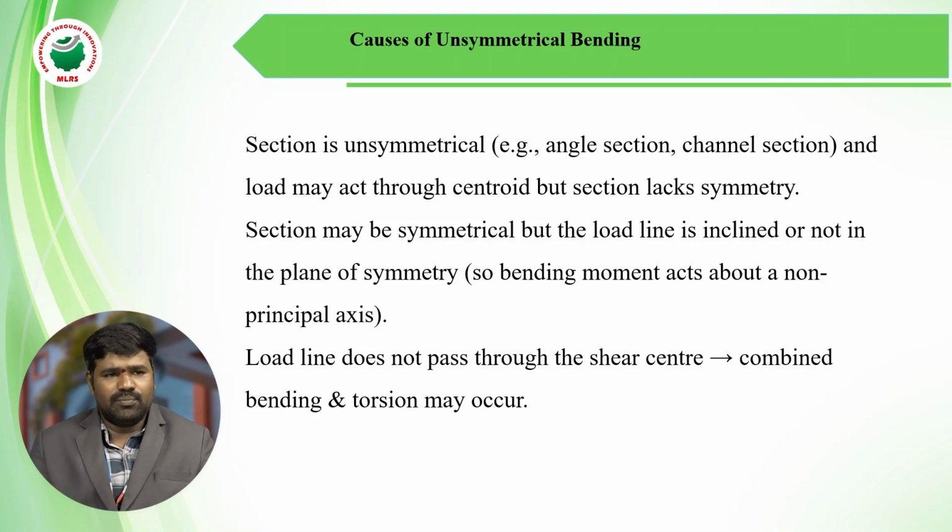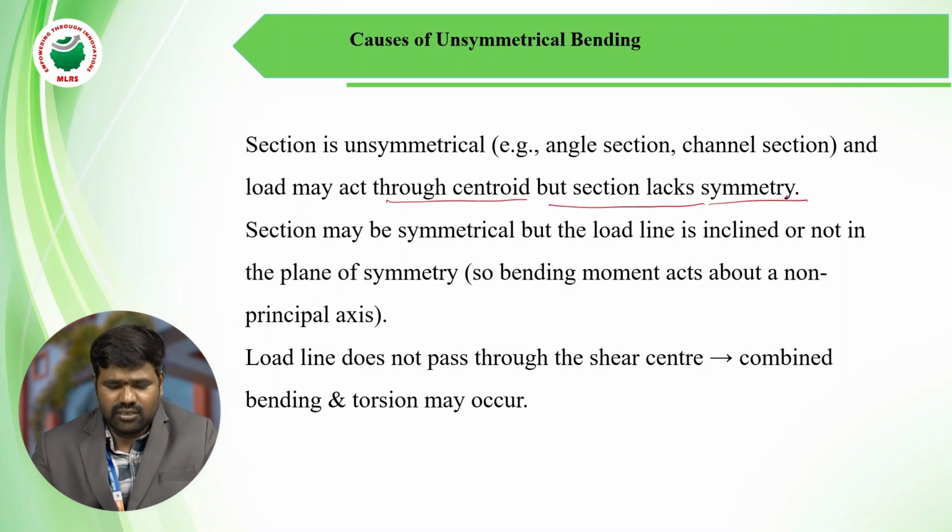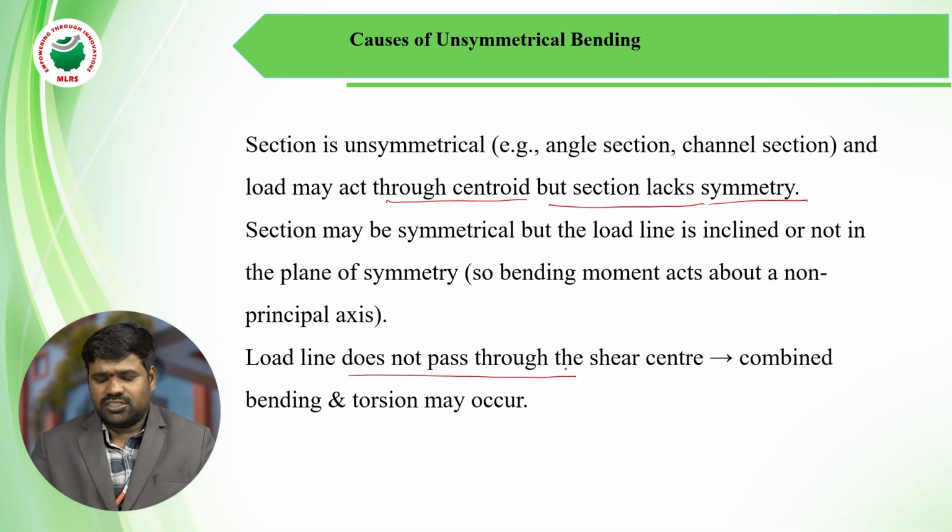The section is unsymmetrical. Examples: angle section, channel section, L sections, different angular sections. The load may act through the centroid, but the section lacks symmetry. Or the section may be symmetrical, but the load line is inclined or not in the plane of symmetry, so the bending moment acts about a non-principal axis. The load line does not pass through the shear center, so combined bending and torsion may occur.